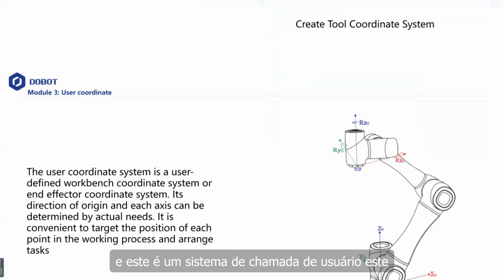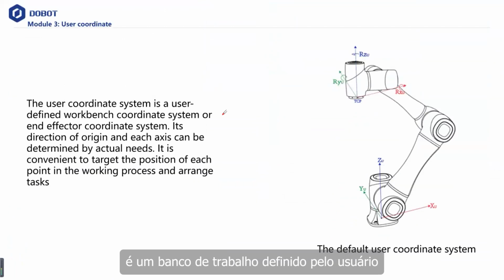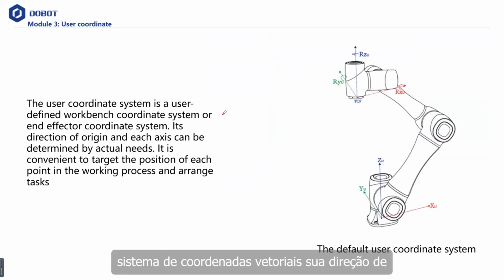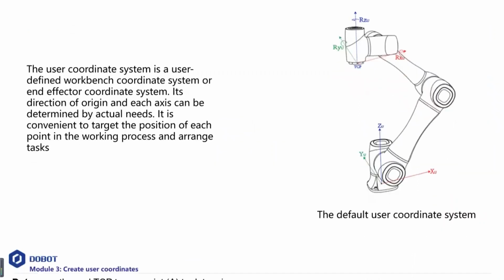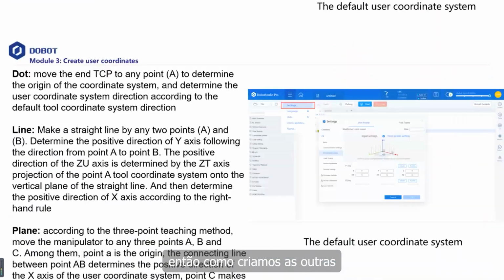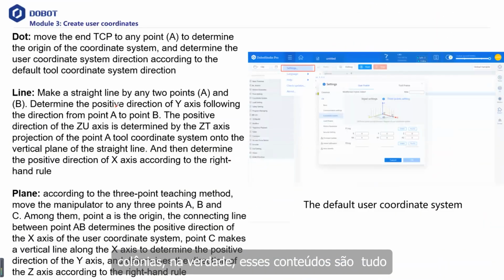And this is a user coordinate system. This is a user-defined working bench coordinate system or indicator coordinate system. Its origin and the direction of each axis can be determined by actual needs. It's convenient to target the position of each point of the working process and arrange tests. So how do we create user coordinates?